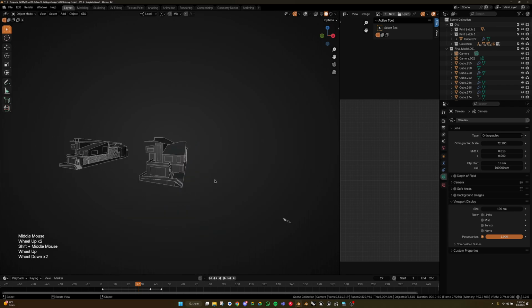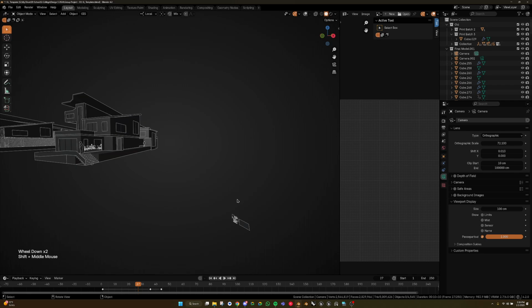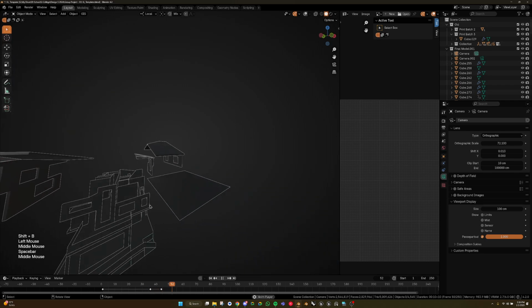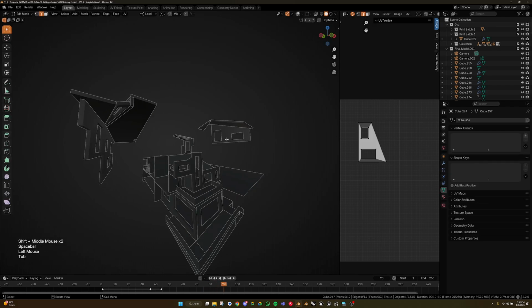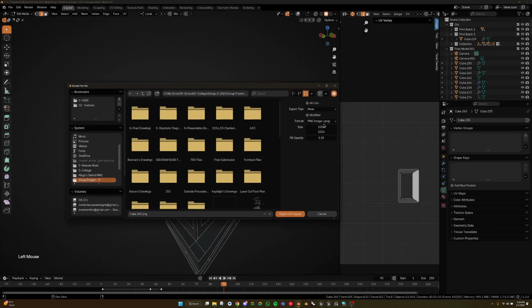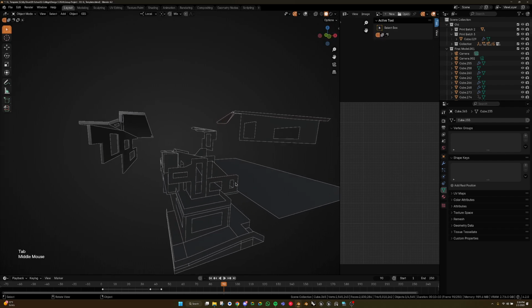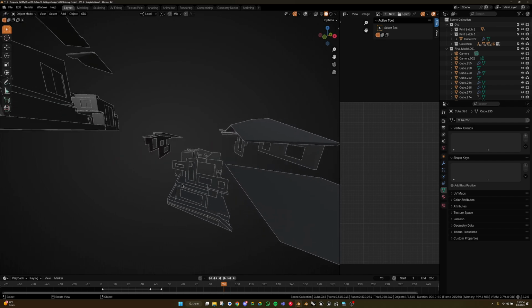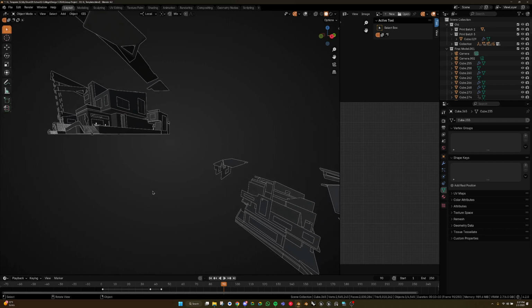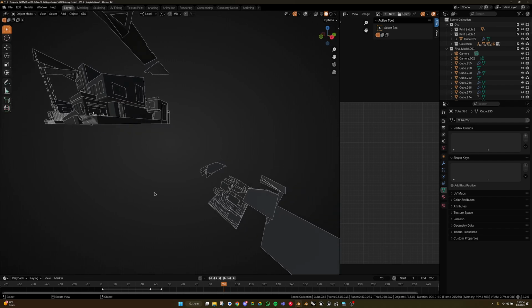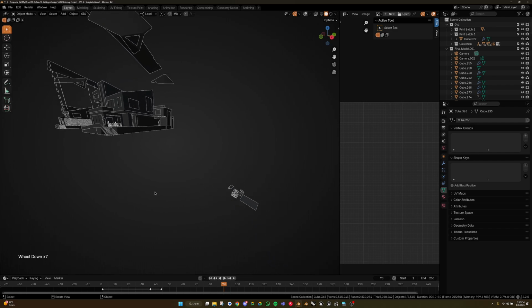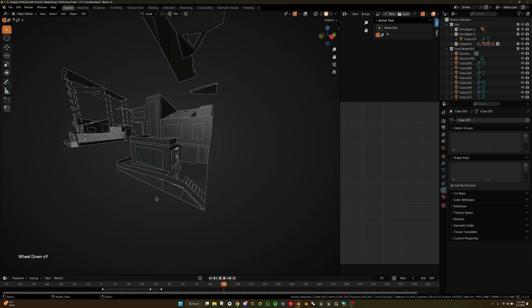And then if you want to scale it down, you can scale it down in Blender. And this is how I do my physical models. I explode it like this, and I take each individual piece. And I do a UV unwrap, and you have this UV unwrap, and you can go to UV, export UV layout. I know this is just a quick overview, and then you can export it as an SVG, scale it, whatever, and then you have your templates to cut out, or laser cut. That's what I do. I have a laser cutter, and you can laser cut all these pieces and put it together, which is what I did. And it was very stress-free. It went together pretty fast, and it was just overall a more enjoyable experience.